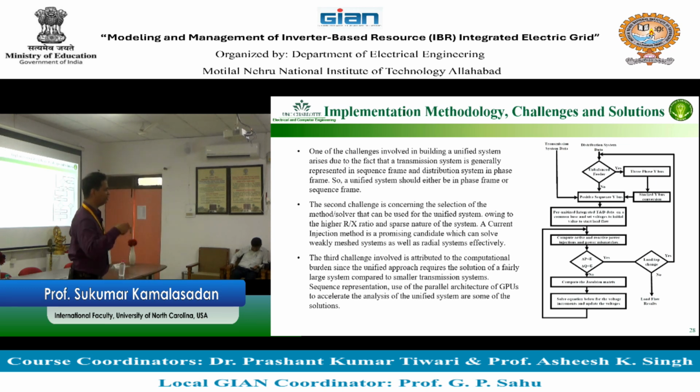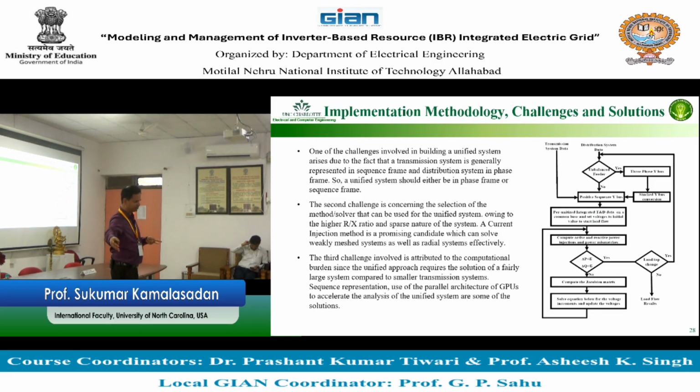So with this approach you can do 3 additional things. Number one, you can include the distribution system as a whole in the unified model. Number two, you can run this approach in a positive sequence mode, which means no unbalance on the distribution side, reduced. Number three, you can correct the unbalance of the distribution system with the negative sequence and bring it back onto the transmission network without having to solve the 3 by 3 big matrix that we used to have to solve for the distribution system. So I'm just giving you one approach for the unified.